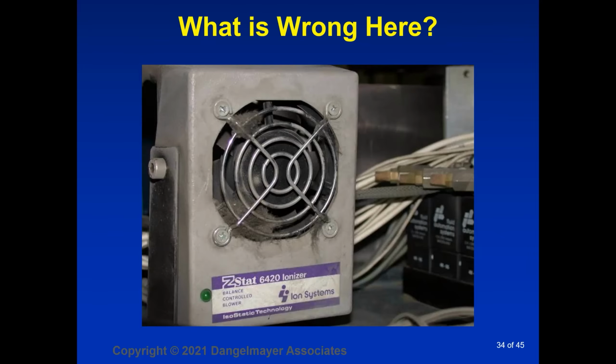Arnie, I just wanted to add a thought here. When we did the event detection, we were, I don't know, 75 feet away, and we picked up the signal. We were way on the other side of the room. Right. You shouldn't have to use an ESD event detector to determine that an ionizer needs maintenance. So basically, go through the process, determine the maintenance interval, and make sure that, whatever you have to do in your company to get it to be part of the general maintenance program, that you actually do that.